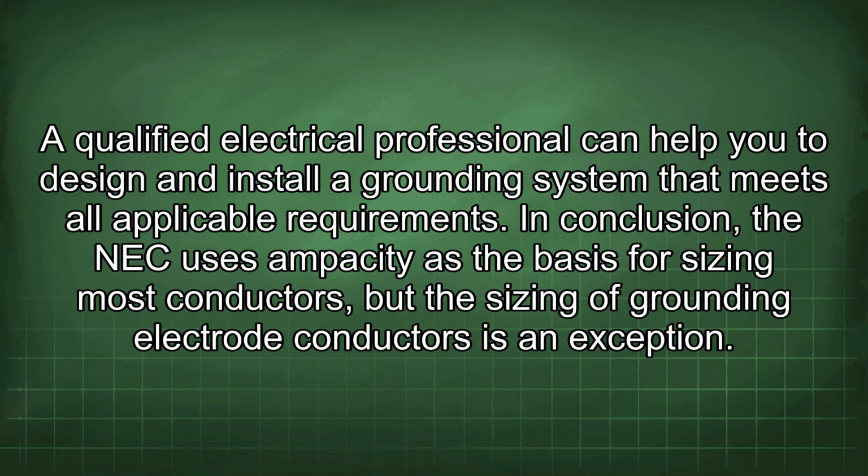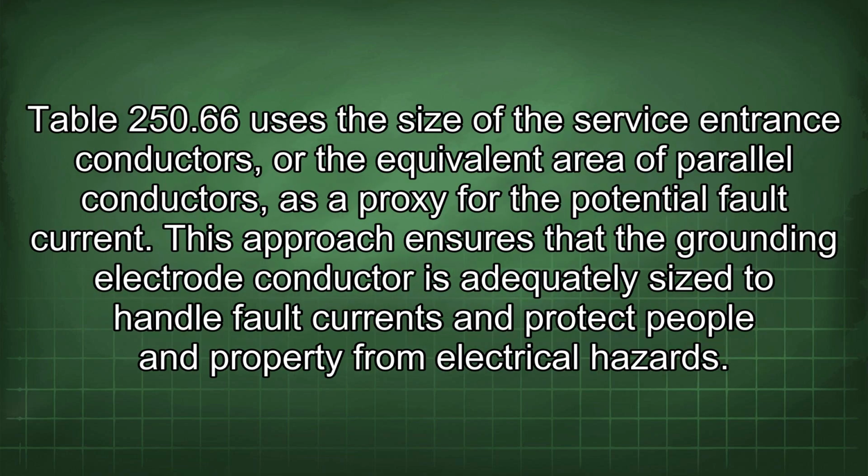In conclusion, the NEC uses ampacity as the basis for sizing most conductors, but the sizing of grounding electrode conductors is an exception. Table 250.66 uses the size of the service entrance conductors, or the equivalent area of parallel conductors, as a proxy for the potential fault current. This approach ensures that the grounding electrode conductor is adequately sized to handle fault currents and protect people and property from electrical hazards.